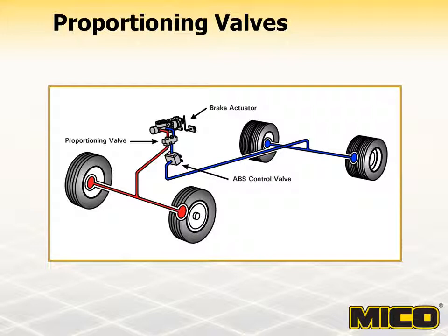The anti-lock brake valve was also designed to control wheel lockup during braking. Basically, an anti-lock brake system monitors the speed of each wheel. When one slows more than the others, hydraulic pressure to that wheel is released and reapplied up to 15 times per second to prevent lockup.